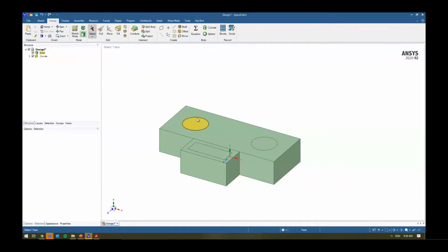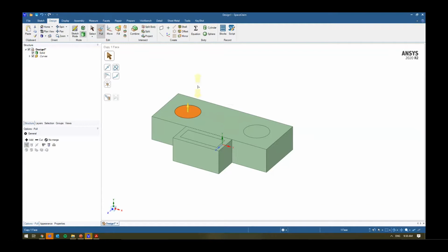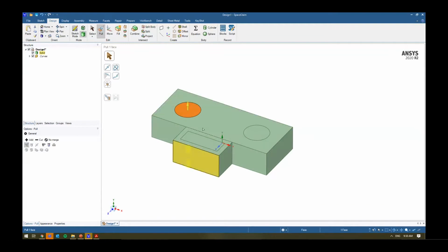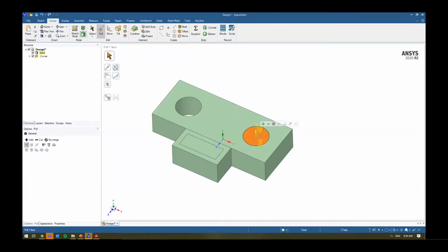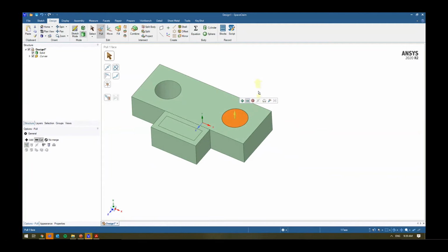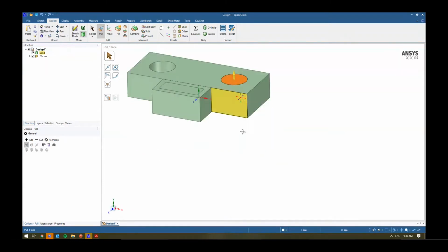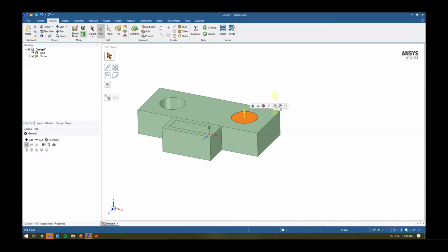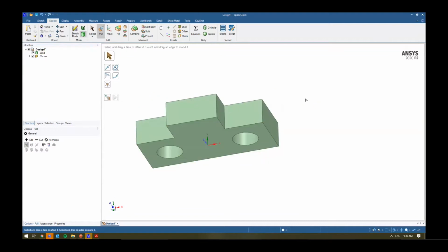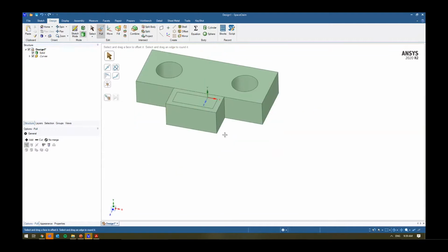All right, now that I've got some surfaces, what I'd like to do is go in and use my pull tool to pull something in. So the pull is a pretty versatile tool. I can pull things in, but I can also select it and use it as a cutting tool as well, right? So I can cut through whatever I've got. Again, similar to before, I can cut through, -5 millimeters. I can cut through using a ruler, right? I want a ruler 5 mil into there, or I can cut through up to a specific surface as well, right? So I can do that.